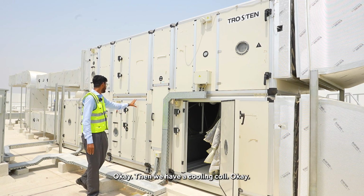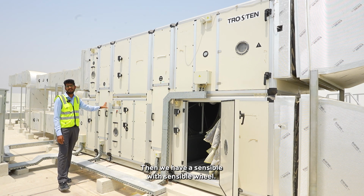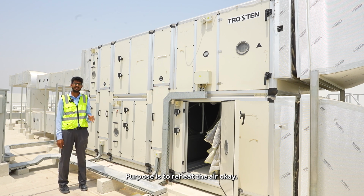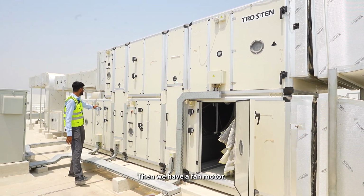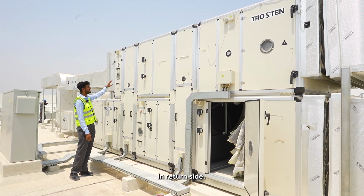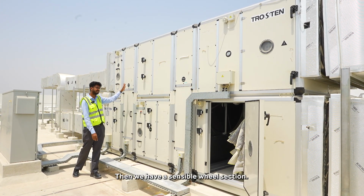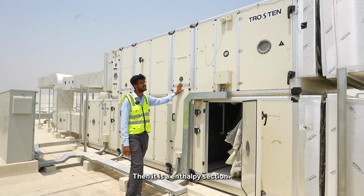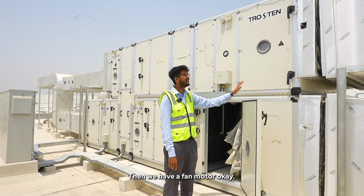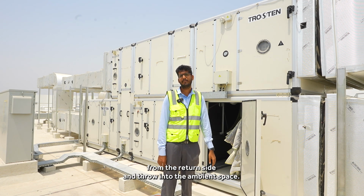Then we have a cooling coil. Then we have a sensible wheel. The sensible wheel's purpose is to reheat the air. Through reheating we are maintaining the relative humidity. Then we have a fan motor. On the return side, as I told you, we have one filter, the pre-filter. Then we have the sensible wheel suction, then a plenum, then the enthalpy wheel suction. Then we have a fan motor. The fan motor will extract the air from the return side and throw it into the ambient space.